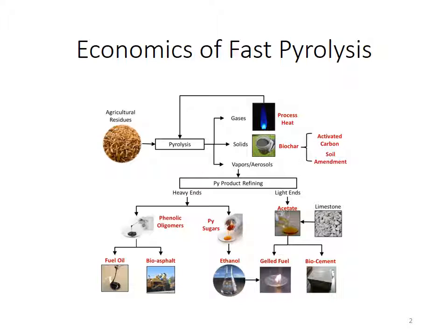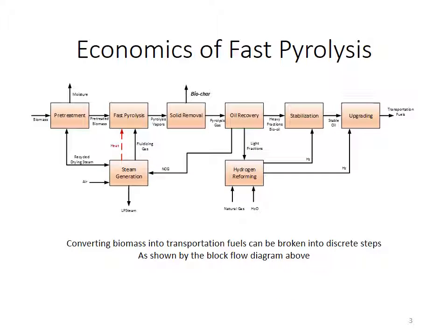Now we'll look specifically at how we use fast pyrolysis to produce biofuels and what the costs are associated with that process. In the case of biofuel production, you can look at the process as incorporating several steps. If you start from biomass, we have to pre-treat it, just as in many thermochemical processes. We dry it and we grind it.